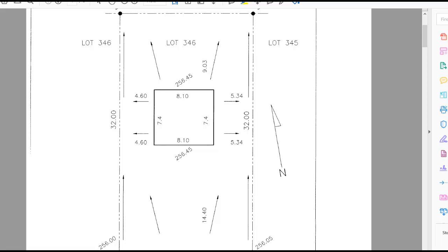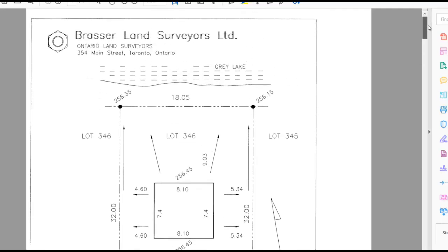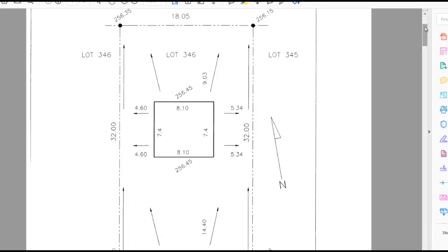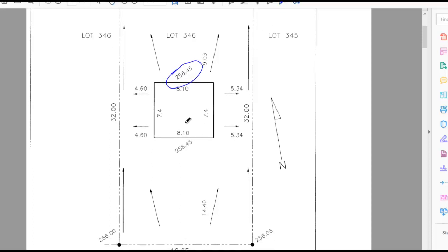Today I'll work on this excavation takeoff project, and this project is given as you can see. These drawings are provided, so you can use them for reference. Now, to start with this project, we go to the site plan, and on the site plan you need to notice the levels, and if the levels are not the same, then you have to take the average of these levels.